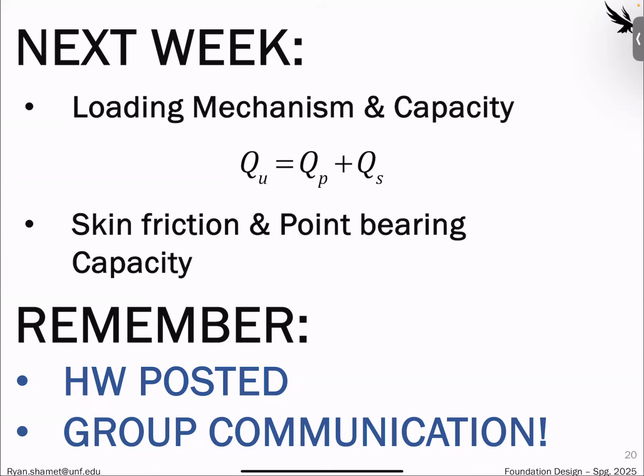To mobilize skin friction, you have to have movement. Friction is only friction if something is moving against it. So that's the tricky thing in design: you actually have to induce settlement. And that's why driving it is beneficial, because you're essentially driving it and mobilizing it, over bored piles where you might have that initial seating and that initial deflection. Okay, so don't worry about these things because we haven't talked about them yet.